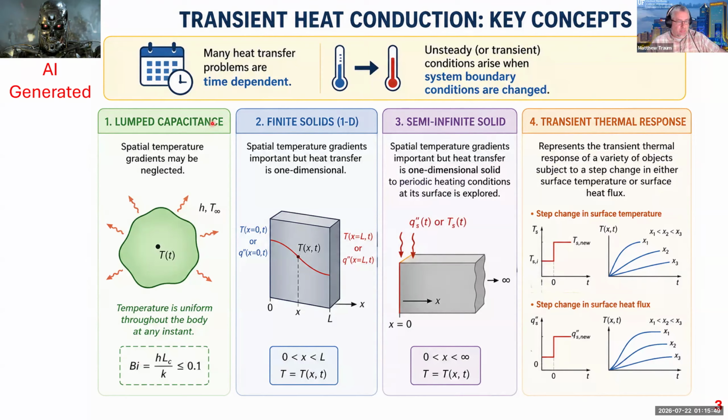And so this is like the holy grail, right? There's a criterion called the Biot number, which we'll get to in this lecture. But if you can demonstrate that this Biot number is less than 0.1, the criterion is met for your object, then you are in a happy place, my friends, because lumped capacitance, you will see mathematically, is really easy. It's relatively easy compared to all these other things. It does involve exponentials and logarithms and a little bit of nasty math, but nowhere near as nasty as these other things. So anyway, that's what we're going to talk about today.